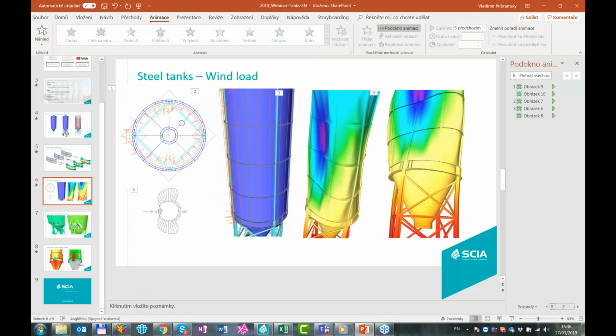The one tip that I can tell you in advance about showing the results of 3D deformation in this case is that 3D displacement shows deformed structures in terms of volumes in the standard setting. You can see that both volumes of the 1D members and 2D members are respected and drawn, and this gives you very realistic touch or realistic behavior of the structure.